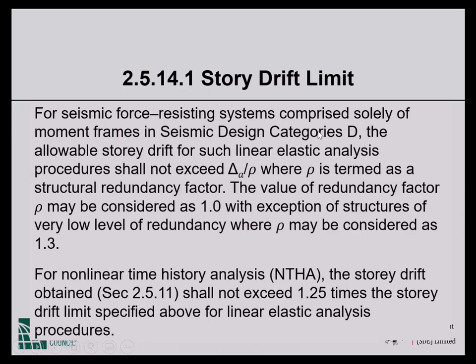The allowable story drift for such linear elastic analysis procedure shall not exceed delta sub A divided by rho. So the bottom line is, if the seismic force resisting system consists entirely of moment frames and your seismic design category is D, your drift limit is not delta sub A. It is delta sub A divided by a redundancy factor rho.